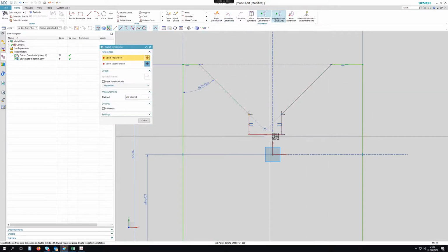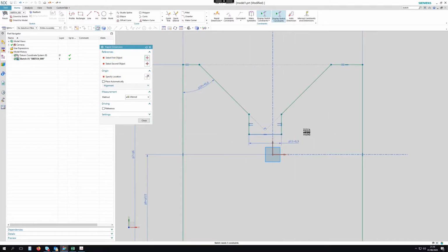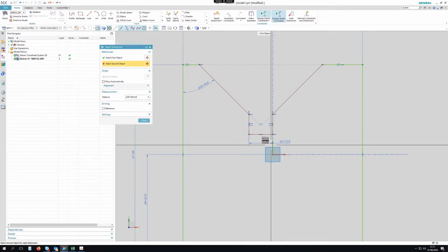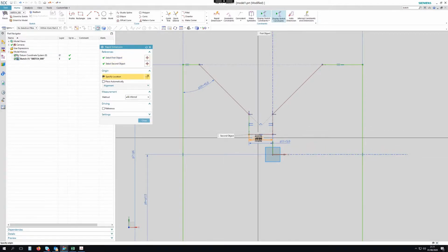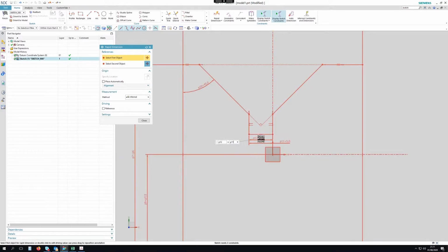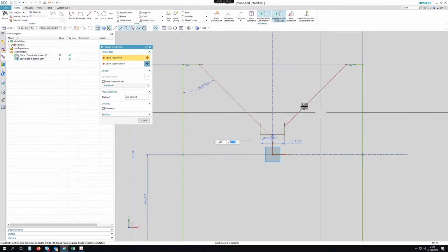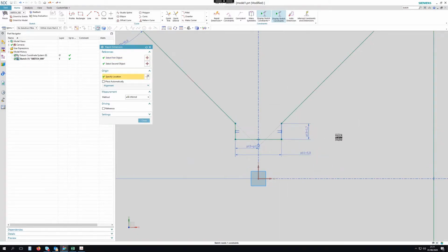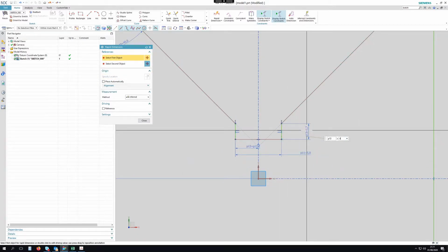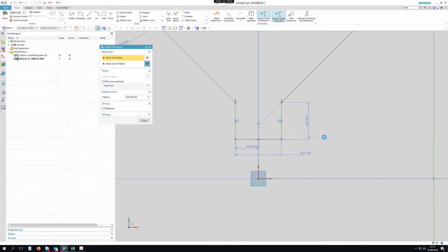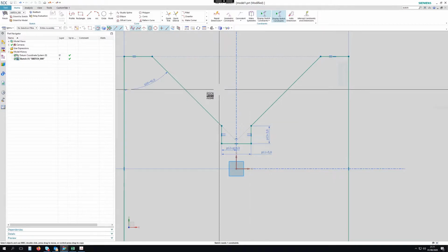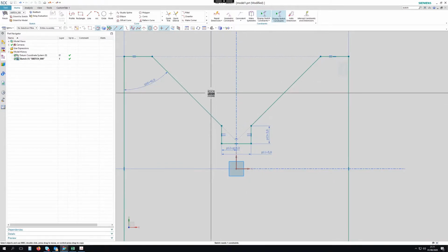Right, so I want to give a size to this undercut. Let's make it 5mm. And from this point to this point, I'm going to say P11 divided by 2. Always want to keep it in the middle, and I'm going to give it a length of this line of 4, maybe 3.